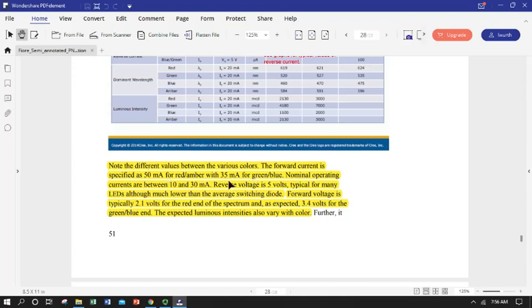Okay, so big things to bear in mind about LEDs. Operate in forward bias. The forward bias voltage that you apply gets a portion to getting charged carriers across the interface and making light. You will have more current through the device basically with supply voltage, but you'll have more light depending on current. So your light is proportional to current flowing through.